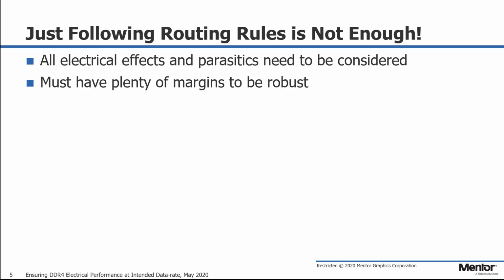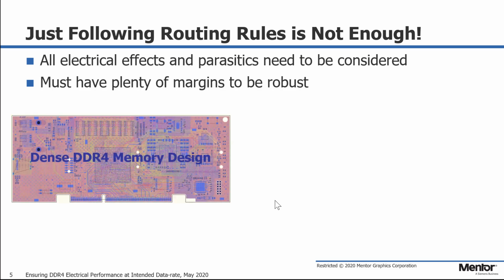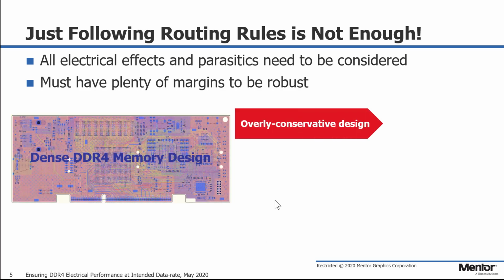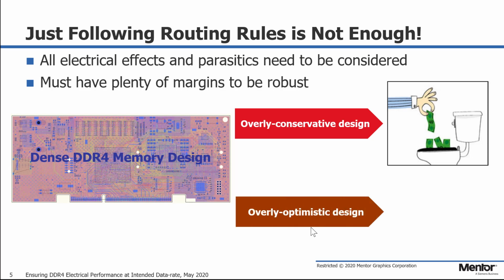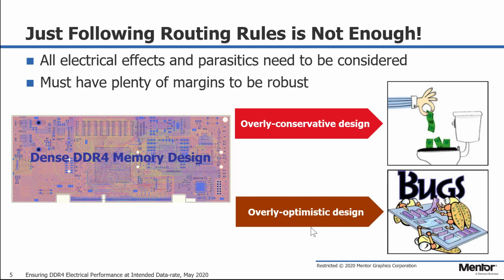You must consider all of the electrical effects and parasitics of the layout and devices, but at the same time, you must have plenty of margins for the design to be robust. Usually, if you over-design, then you might be wasting your resources, but if you under-design, then you might run into consistent or sometimes intermittent issues in the lab, or even worse, you might only find the problems during the production.